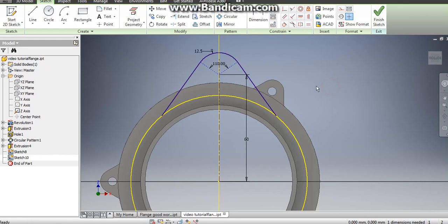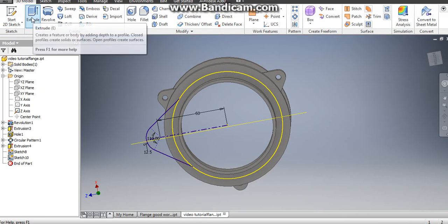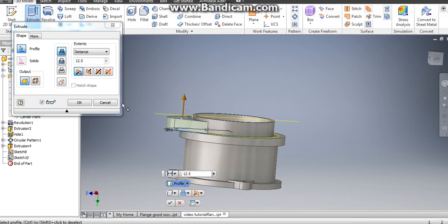Right click and select OK. Finish your sketch. We're now going to extrude that second style of wing. It's facing the wrong direction right now. Change to an extrusion from a cut. The distance is 12.5 millimeters. We click OK.